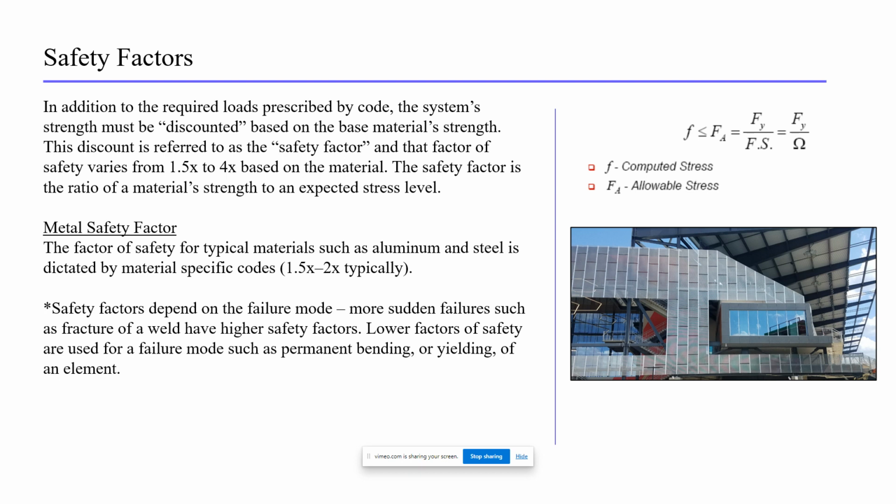Per IBC Chapter 17, which deals with testing, it's only suggested or required if the materials and construction are outside the scope of IBC or the standards therein. So testing should not be used as a substitute for engineering is the takeaway.